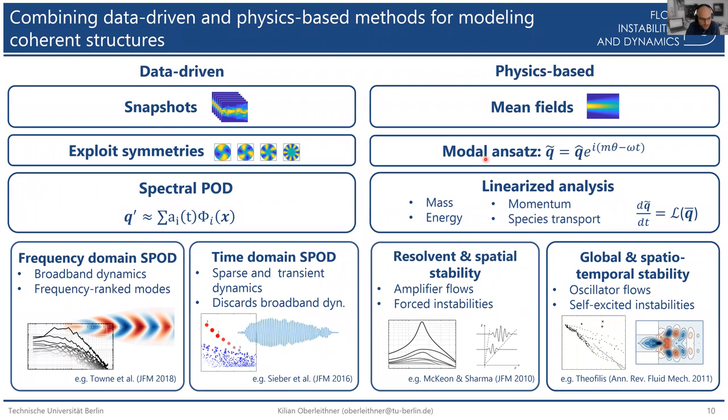I wanted to have this all on one slide to briefly make clear that there are some connections between these two worlds here. The frequency domain SPOD combines very nicely with the resolvent type analysis or local spatial stability analysis, while the time domain SPOD combines really nicely with the global mode analysis.